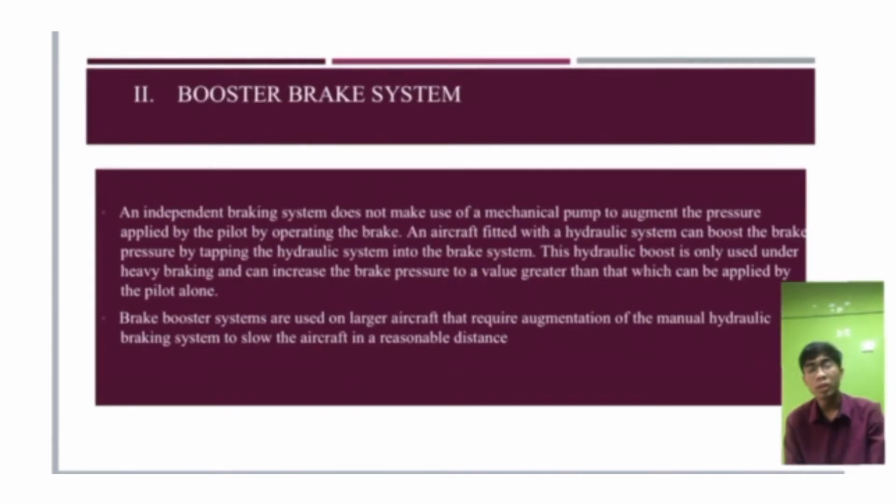Second, booster brake system. An independent braking system does not make use of a mechanical pump to augment the pressure applied by the pilot by operating the brake. An aircraft fitted with a hydraulic system can boost the brake pressure by tapping the hydraulic system into the brake system.